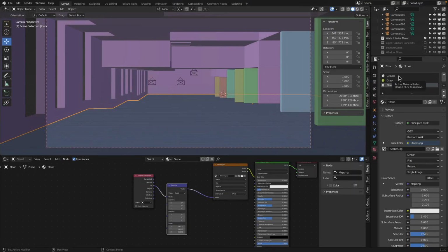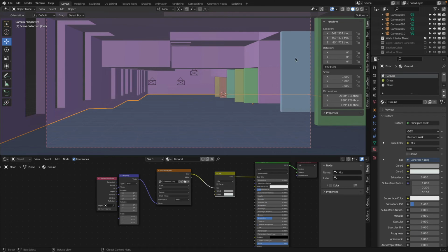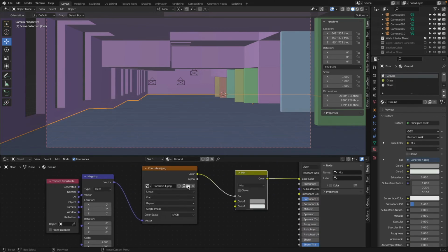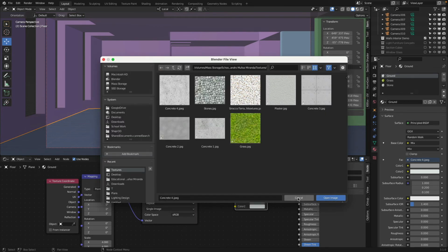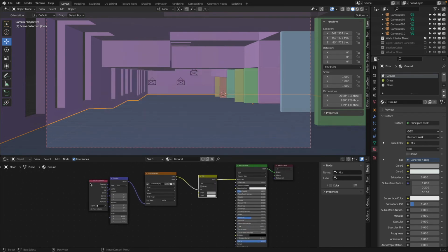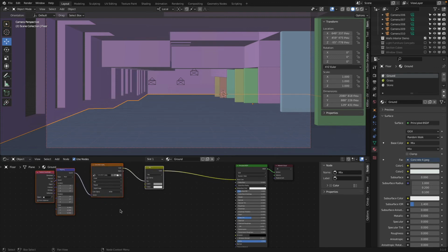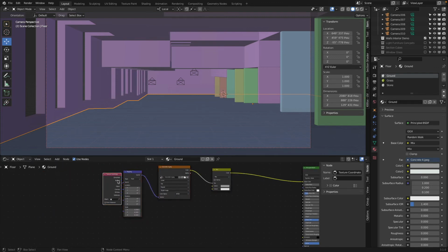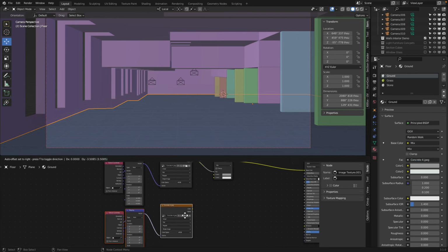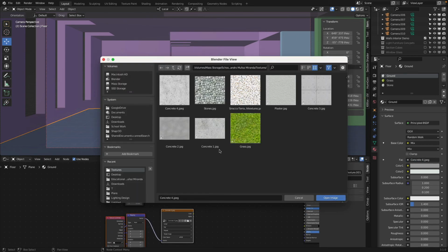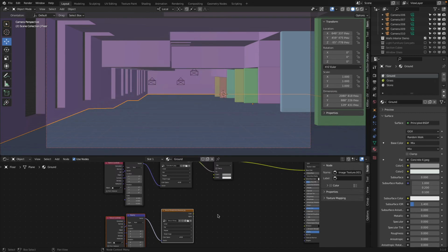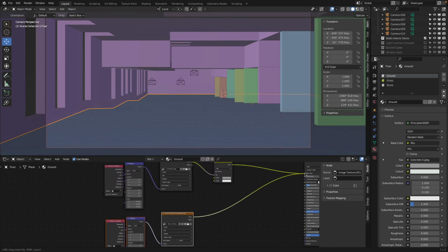So go to ground. Is this okay? I want to make sure that's not the same material. So here, this concrete, now I will, hold on. Actually, I really like the way this looks. Check this out. Okay. So I move this to the side. With B, I select everything. With G, you can move. This I select, Shift D, make a copy. Click on this. There's my other material. And then I drag this one in there.